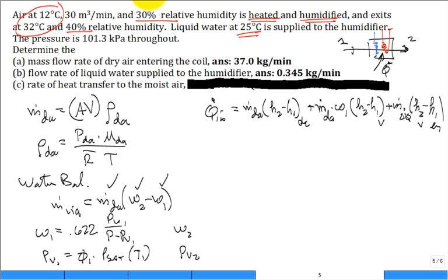Okay, so how do I get the enthalpy of the dry air at the exit temperature? What temperature is it going out at? 32 degrees C. And this is the enthalpy of the dry air at 12 degrees C. How do I get those two? Air tables. Professor, could I use C sub P delta T, make life a little easier? Sure. That'll be very accurate as well. Encourage you to do it both ways in homework so you're very familiar.